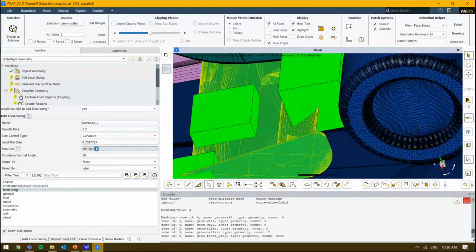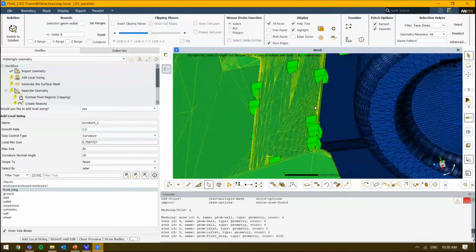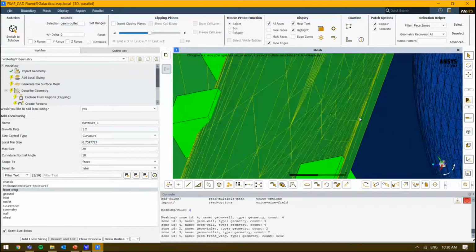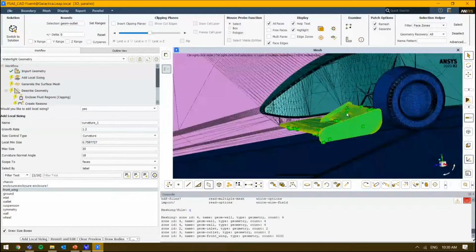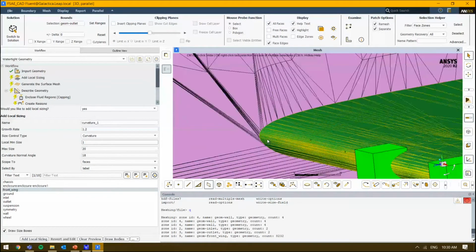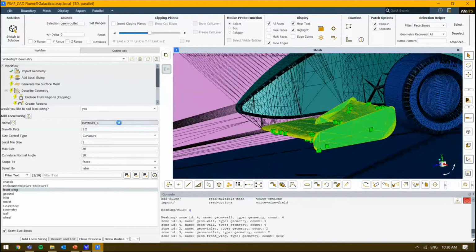The small boxes, let's just change this to something like 20. All right, so it's like a preview. Small boxes you can see are these ones over here, right? Now, what happens is that around here, I want a lot of elements across there. So maybe let's leave this as 1 for now, and we'll make some changes to that a little bit later on. We'll kind of play around with it, right? So I can do that. Let's give it a specific name as well, so I know exactly what I want.